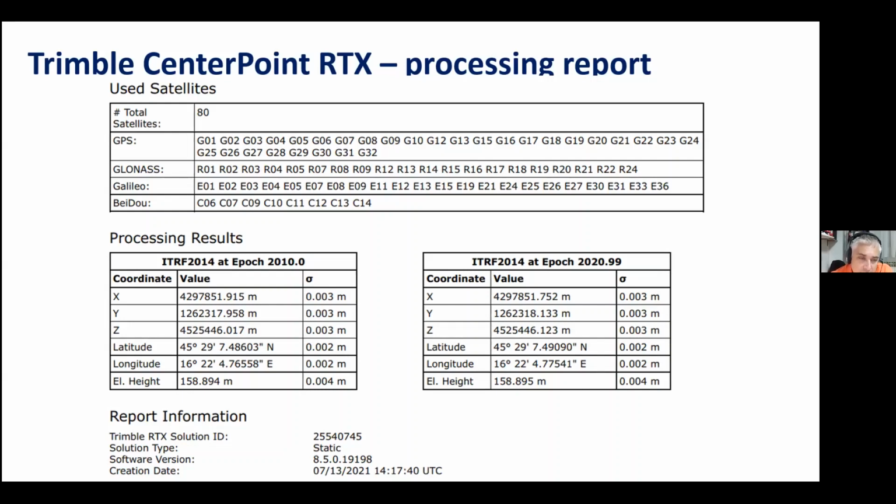The results are given in XYZ Cartesian coordinates with the precision estimate given by standard deviation, and of course XYZ are transformed or converted into latitude, longitude, and ellipsoidal height, with of course the belonging precision estimation.